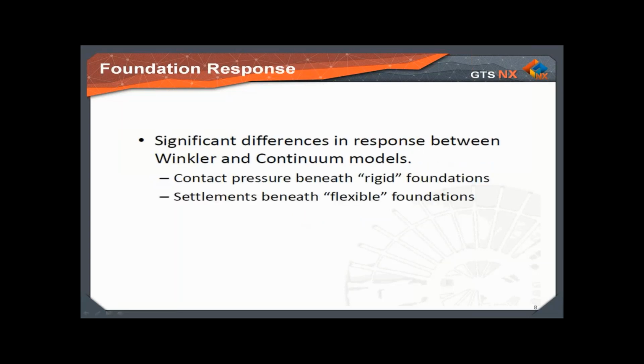Now the foundation response. The significant difference between the Winkler and continuum models is as below. This can be demonstrated easily by examining two extreme situations, a rigid foundation and a flexible foundation. You will see the contact pressure and settlement between these extreme situations.